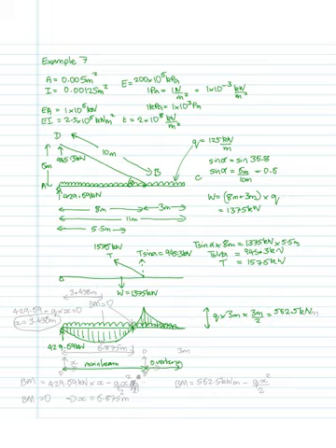So the equation for the real beam would be 429.69 kilonewtons multiplied by x, taking our x coordinate from that point there for the main beam, and that needs to be minus q times x squared over 2 because of the UDL.